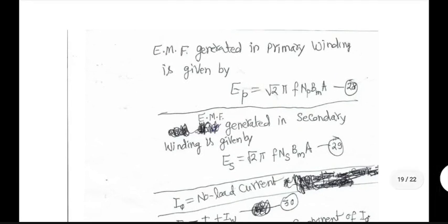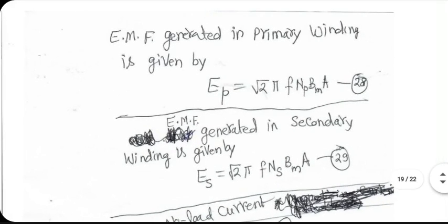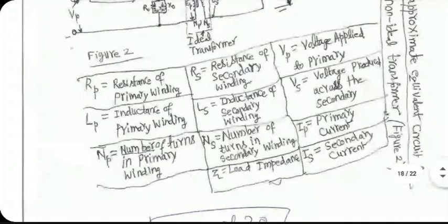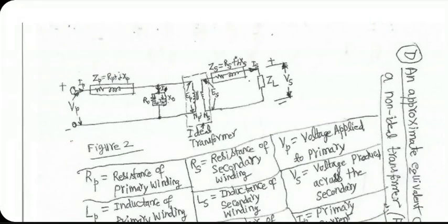We have got these formulas for EMFs already. So I'm repeating them here for the sake of reference. For a lossless case, EP and VP were the same. So I was calling them VP and VS there, because ES and VS are also the same. But for a lossy case, it is better to be aware that these formulas apply to EP and ES, not to VP and VS.